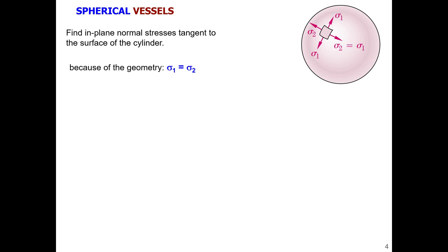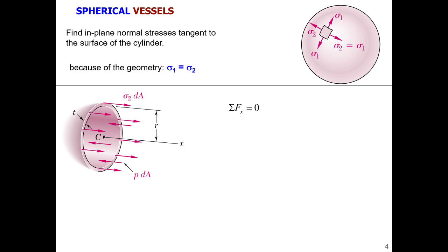Okay, so well, our standard course of action here would be, of course, to consider equilibrium equations. And this is our schematic for that. So we have this cross section, right? So put our axis in direction x, and we will calculate the balance of the forces, and they need to be 0 if we are in equilibrium. And again, we have two contributions here. So the fluid inside, or some substance inside, pushes this sphere in this direction, right, opposite in the direction of x. And the other part of that spherical shell, this material from this side that we removed, pulls it back, and so to keep it in equilibrium on this small part where we have the material, right? And so that will be connected to that sigma 2, and again multiplied by the area, very similar to what we just considered.